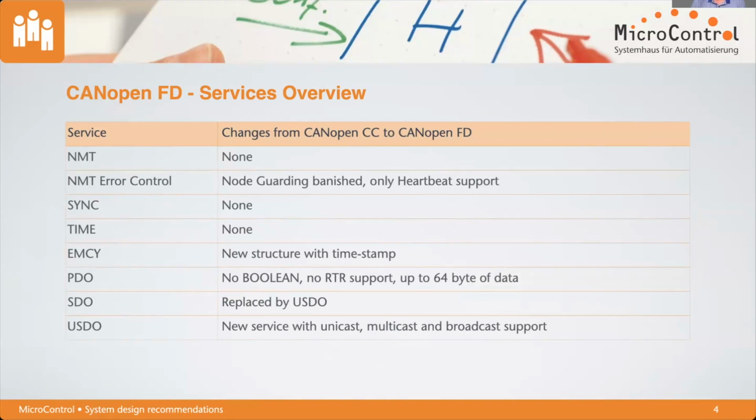If you're a newcomer and you just want to start with CanOpen, my recommendation is to start directly with CanOpenFD, and you don't have to care about these slides. What I'm saying here is what the changes are that you have to keep in mind when you design a system, you have experience with classical CanOpen, and you move over to CanOpenFD.